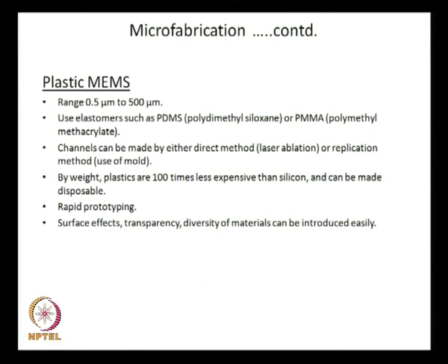Channels can be made by either direct method, that is laser ablation, that means you take the plastic material and then you selectively remove a portion which will form the channel. So, you take a plastic plate and then selectively remove a portion using laser ablation.